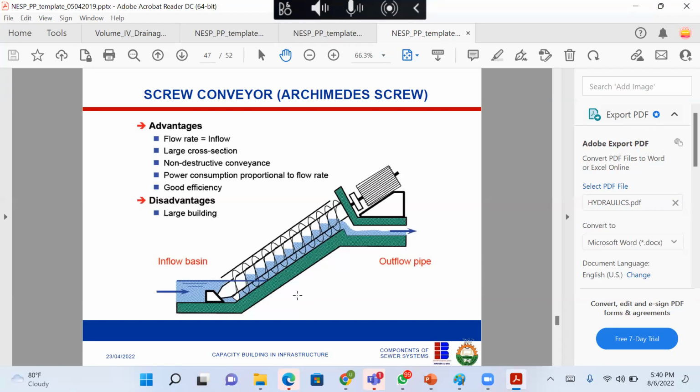The reason is that when you design your wastewater system, you design by gravity. So for the water to get to the treatment plant, it's more likely to arrive at the lowest level. So you have to now lift it back up. Like in Abuja, the difference in elevation between the city center and the treatment plant is about 12 meters. Some can go as high as 18 meters. Then you need to pump it back to the level of the treatment plant. Meanwhile, every treatment plant is usually located at the lowest level. That one is constant.